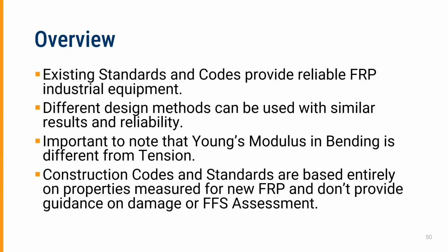Different design methods can be used with similar results and reliability. It's important to note that Young's modulus in bending is quite different from tension. And construction codes and standards are based entirely on properties measured for new FRP. And they don't provide guidance on damage or fitness for service assessment.